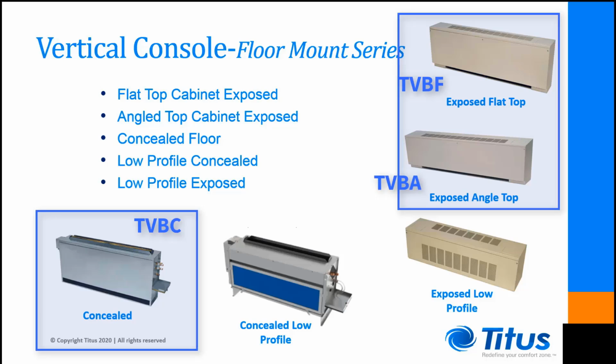These units have similar performances and CFM ranges as the low-profile horizontal units, approximately 200 to 1100 CFM range, but the TVBA and TVBF units, you can see, are not meant to be ducted like the low-profile horizontal units. The TVBF and the TVBA are meant to free blow conditioned air directly into the occupied space. This free blow functionality goes along with the fact that we can see they are painted units. As discussed earlier, painted units are meant to be seen by the persons in the occupied space.